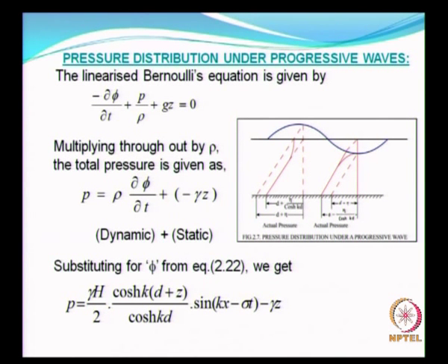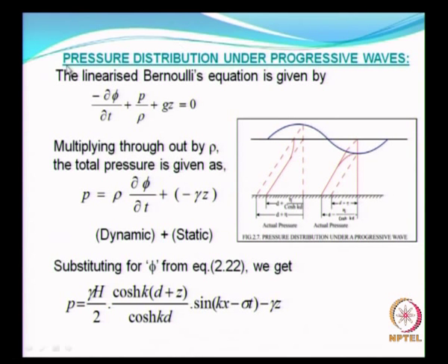So as I said earlier, we are dealing only with the linear theory, and we have linearized the Bernoulli equation, which will be used for defining the pressure distribution under the waves. So here is the linearized Bernoulli equation, and the pressure distribution is shown here in this picture.